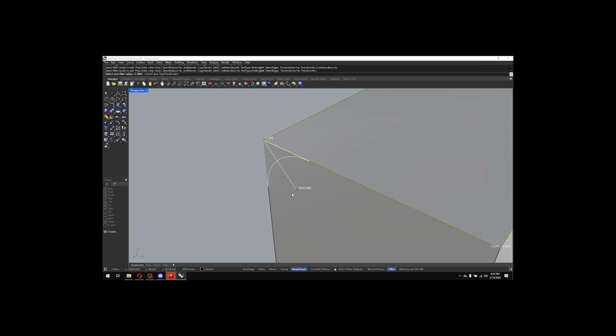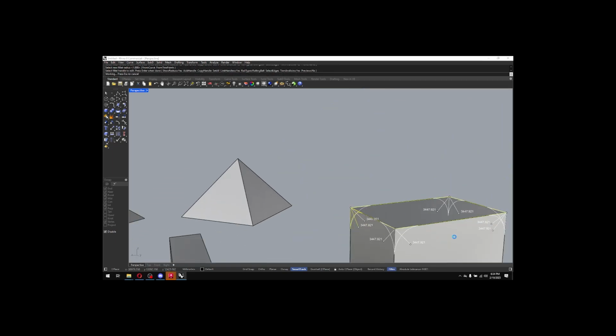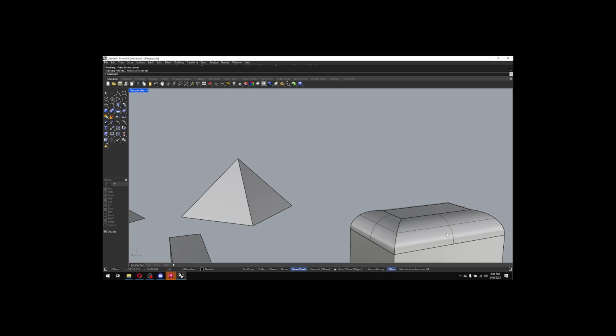And we want select fillet handle to edit. We're going to click on that one. If I start to pull that out, it shows what that size is going to be. So I'm just going to click there. Now we start to see how it's picking up all the corners, which we want. And we hit enter, and then it kind of made like a little dome for us. So it needs practice to pick up which ones you need to go to. Because fillet's really handy. That's how I make a lot of shapes that have sort of standard corners and things like that.